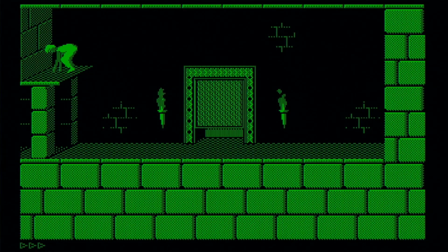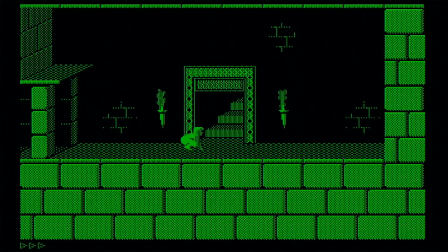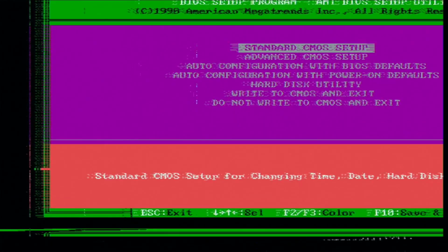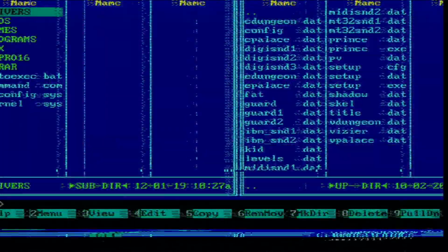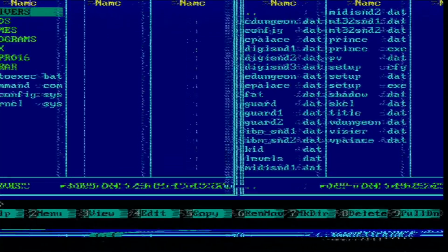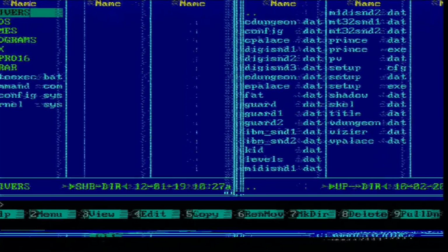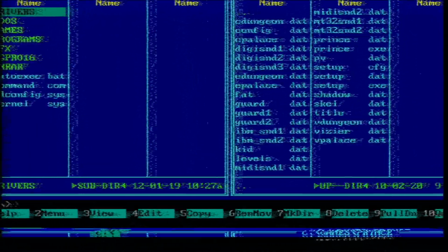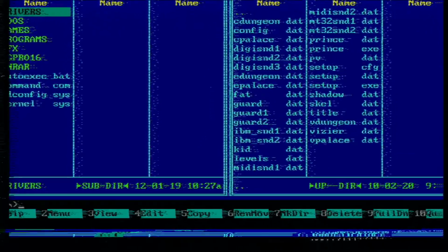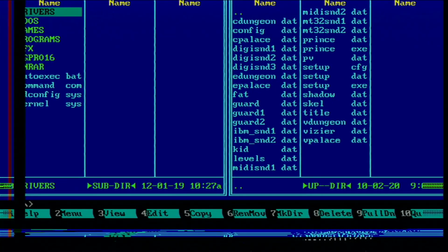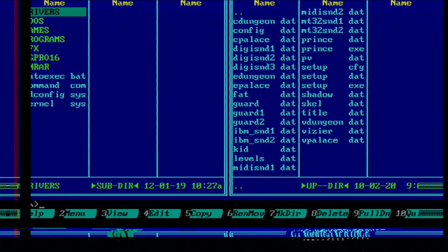What about 64 colors high resolution EGA? Let's again change to the EGA card and see what we get. Well, this doesn't look very good. After restart, we can clearly see that the image is in high resolution, but the image is very unstable and heavily out of sync. As soon as it was stabilized and I tried to start something, GBS 8200 instantly got out of sync again. So I couldn't make any proper tests in this mode. The problem is not the MCE adapter, but rather GBS 8200. The explanation will follow in a moment.